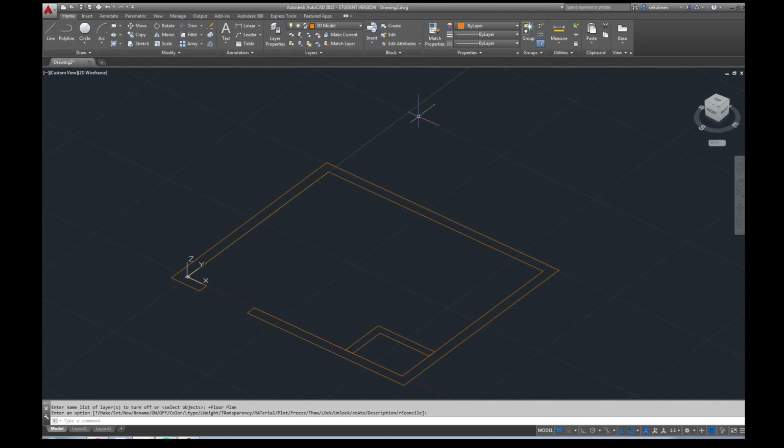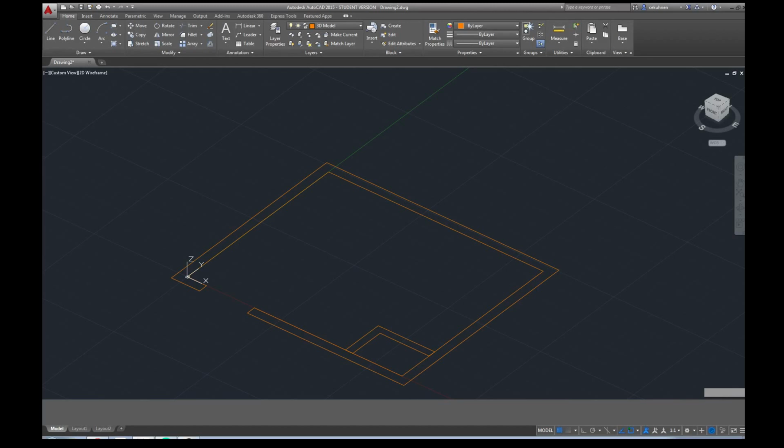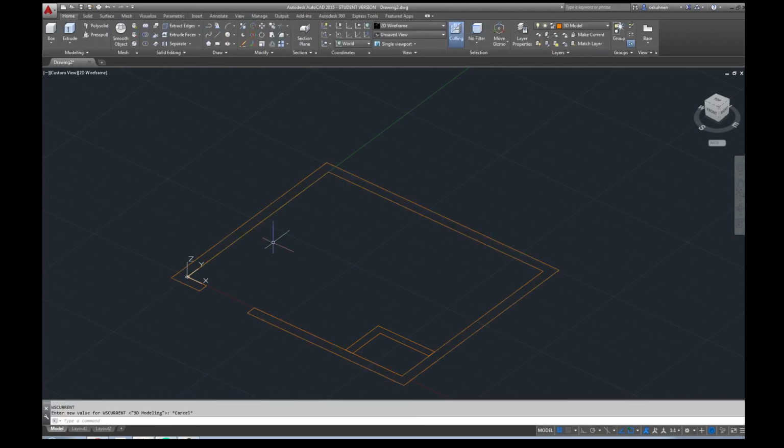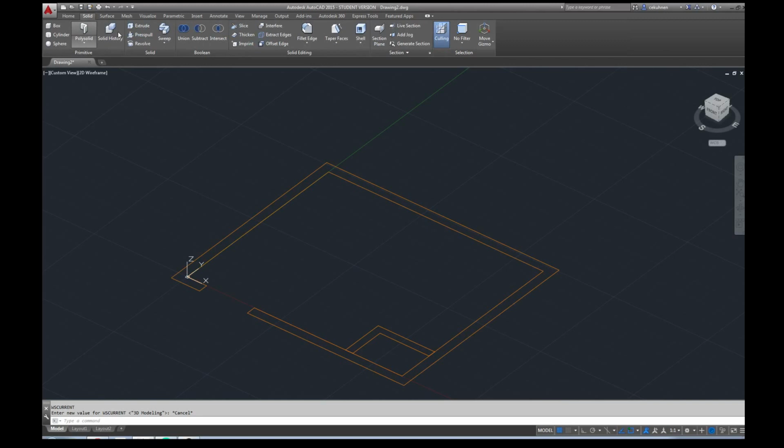And before we now create any geometry, we have to do two things. We should maybe go to 3D modeling because that's our new environment. And then we want to turn on solid history. So to do this, we can simply type SOLIDHIST and AutoCAD completes it. Press enter. 0 means it's off, 1 means it's on. Okay. And the next step is SHOWHIST. Default is 1, type 2.